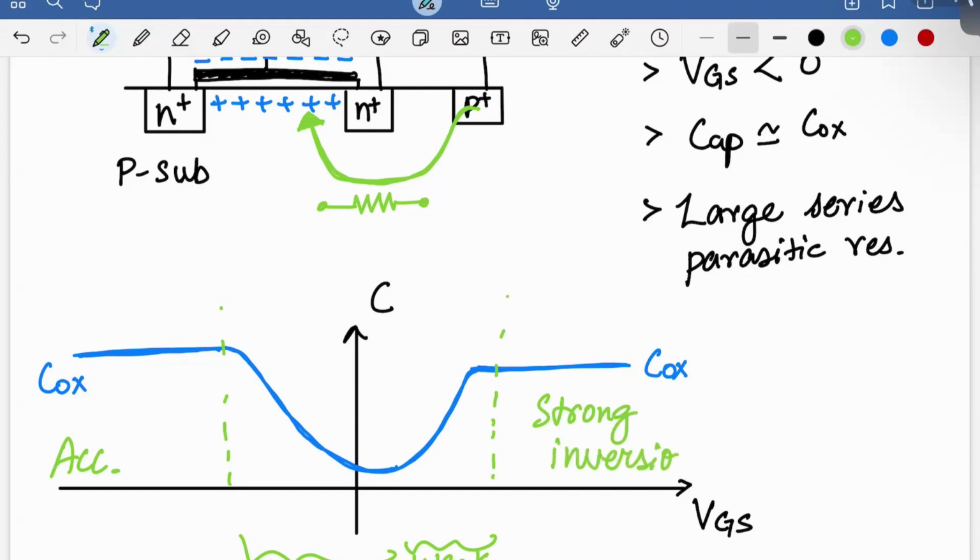Of course, you can subdivide it further to say weak inversion, moderate inversion, and strong inversion, but essentially that's what it looks like. And this is actually kind of undesirable, because if you have a very large swing, then you may be swinging in this region, and you don't want the capacitance to go back up when the voltage drops. Ideally, you would want a curve that looks like this, that's monotonic, or that looks like this.